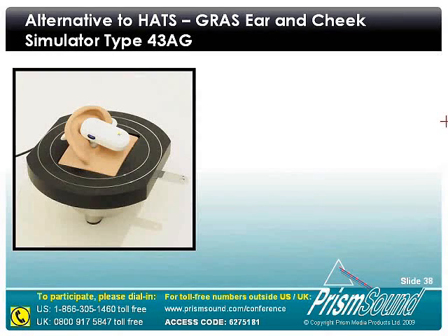Now, the observant ones amongst you may have noticed that in the photograph of my test setup, I wasn't actually using a head and torso simulator at all. I'm actually using an alternative, which is called the ear and cheek simulator. This particular model, again, is from GRAS, the Danish manufacturer, and this ear and cheek simulator allows us to make measurements on the loudspeaker components of the headset, in other words the earpiece that is attached to the ear or in the ear or around the ear.